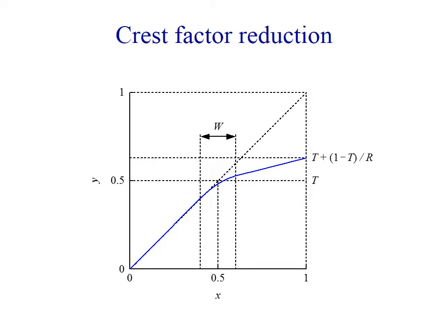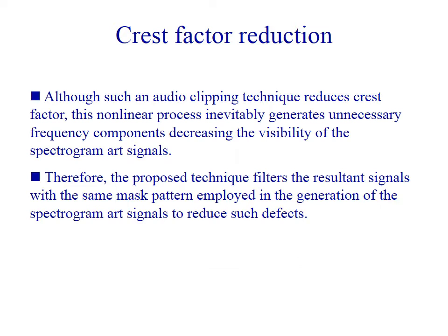A compressor works with a mapping function that defines the relationship between the input and output signals as shown in this figure. Although such an audio clipping technique reduces crest factor, this nonlinear process inevitably generates unnecessary frequency components, decreasing the visibility of the spectrogram ART signals. Therefore, the proposed technique filters the resultant signals with the same mask pattern employed in the generation of the spectrogram ART signals to reduce such defects.